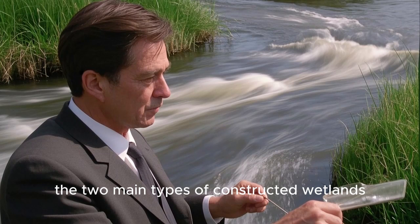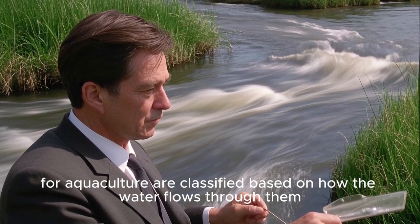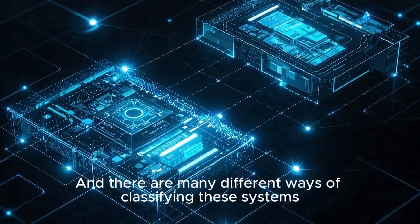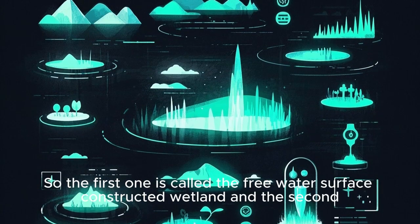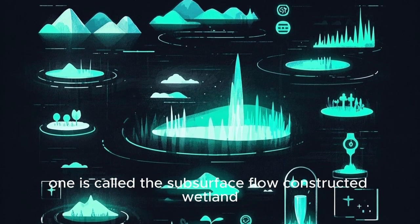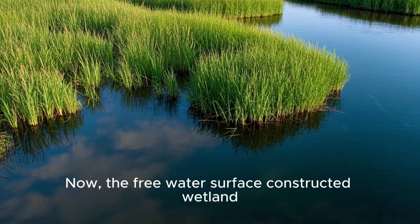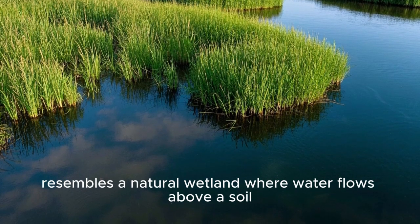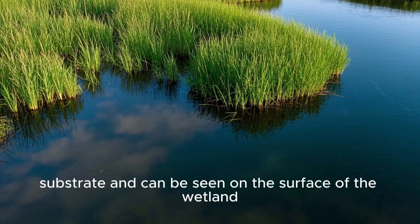Now, the two main types of constructed wetlands for aquaculture are classified based on how the water flows through them. There are many different ways of classifying these systems, but we'll keep it simple today and just look at the two main ones. The first one is called the free water surface constructed wetland, and the second one is called the subsurface flow constructed wetland. Now, the free water surface constructed wetland resembles a natural wetland where water flows above a soil substrate and can be seen on the surface of the wetland.